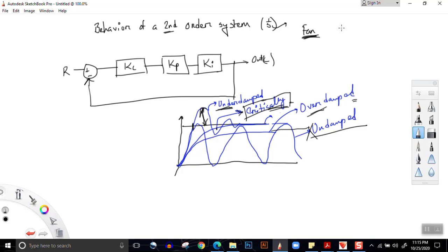Is the case the same if you use a crane at a construction site? In the case of a crane, if there is a delay in work, that's not a problem, but stability is a big issue. A crane always lifts very heavy stuff. If there is a jerking, the stuff can get detached and hit anyone and cause an accident, or break the stuff, and all sorts of things. So in the case of a crane, we actually prefer the overdamped system.